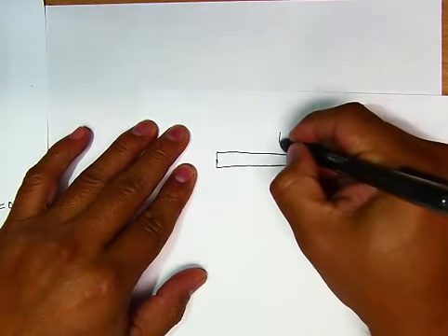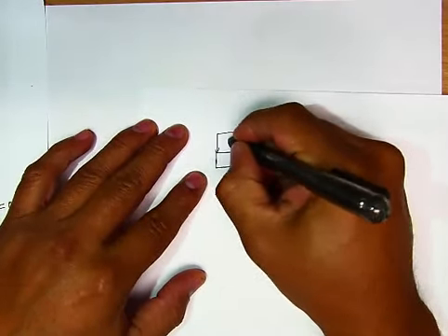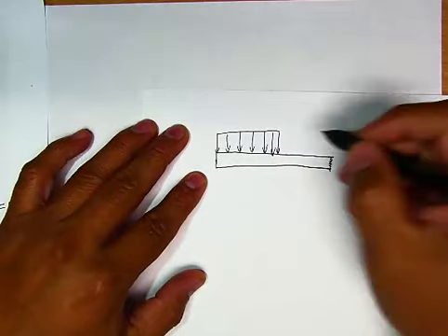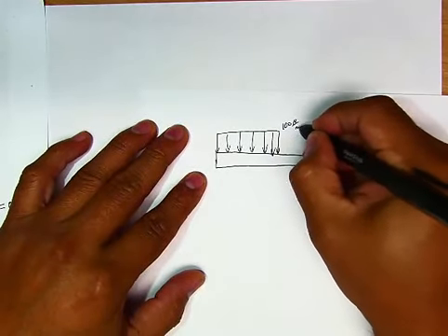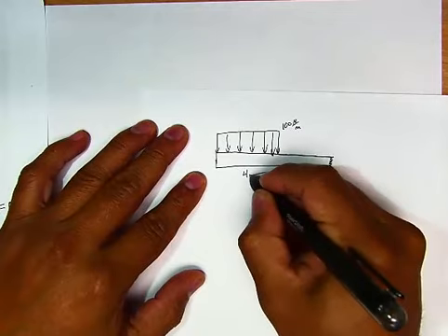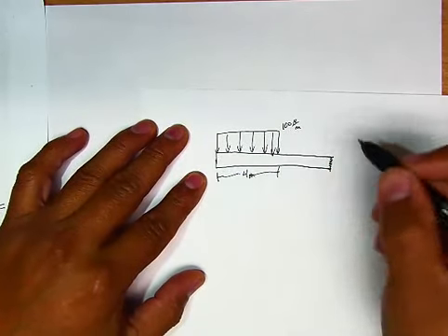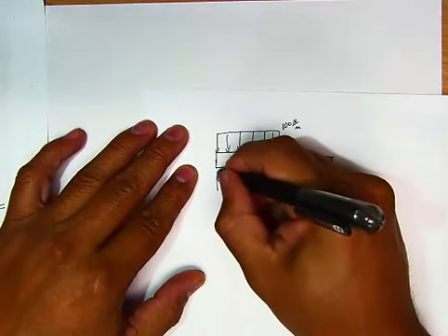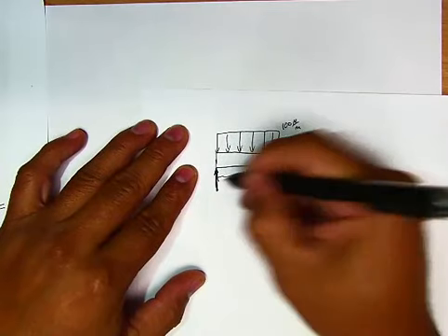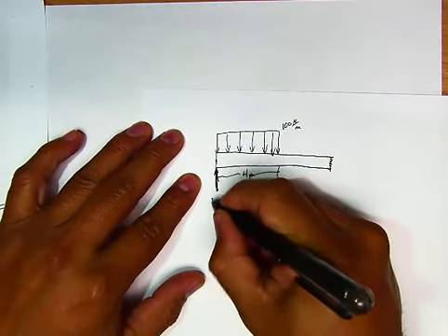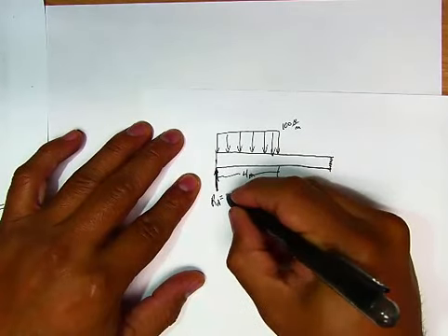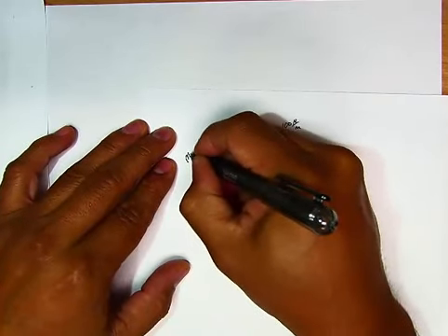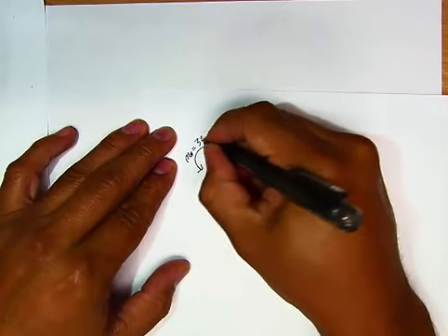There you go. We did originally have a distributed load. And since I already know that that distributed load is 100 newtons per meter, and it is through an entire distance of 4 meters, I'm going to go ahead and replace this in another drawing with one resultant force. But not right now. Again, I want to take my sweet time, baby steps, and show you everything that is happening. My reactive force at A, going up, 700 newtons. My reactive moment at A, MA, which is 3,200 Newton meters.